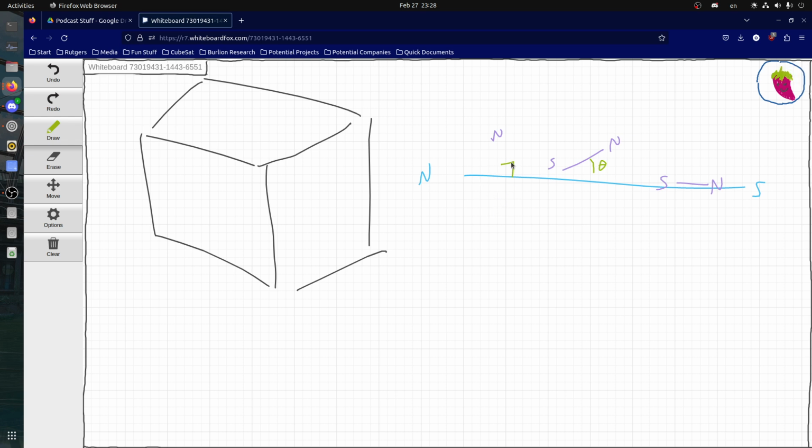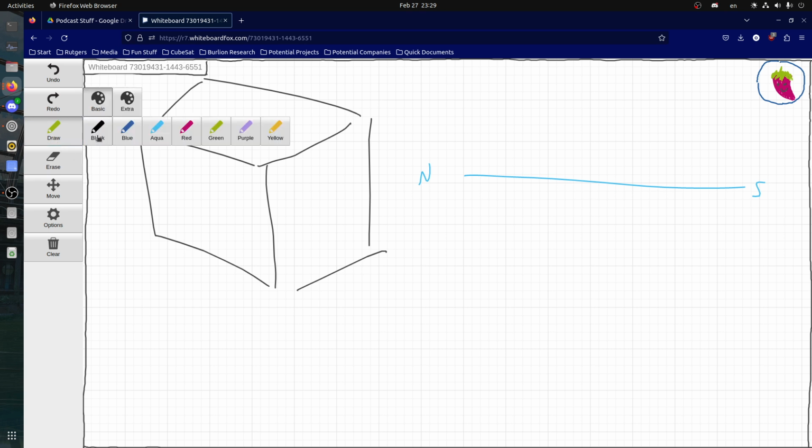Right. So do the magnet torquers only have the most profound effect during detumble? Normally they're just used in detumble. There are papers out there that say it's possible to use them like a reaction wheel system where it can point in all three directions, but I don't think I've seen a mission do that yet. Or if I have, it's only in the experimental phase, not really a trusted idea. But it's usually used in detumble, and also for when your pointing requirements aren't very strong.